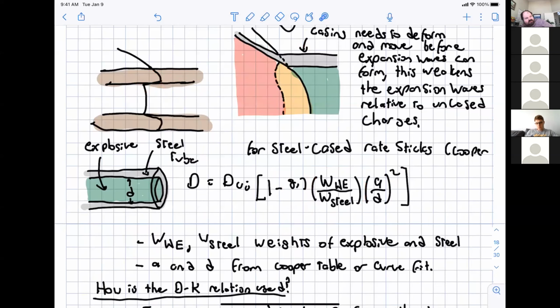I had a colleague who took a class at Princeton for rockets, and when we get to the multi-phase aspect of this class and discuss particle combustion, both per unit mass and per unit volume, burning and from an ignition standpoint, Be particles or beryllium are the perfect material. They have a huge amount of energy. They burn and they burn up easily. Unfortunately, the reason that they're not used in rocket propellants as an additive is that their combustion products are toxic.